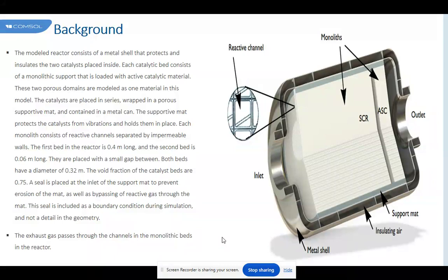Since heat is transferred to the exterior through the carcass, the ring monolith is expected to have a lower temperature than the core. Let us call the hot region the zone with temperature above 500 Kelvin. Slight differences can be seen when the core monolith is 900 per 2.5, where the hot region covers almost the whole core. At the same time, the cases with a 400 per 6.5 monolith in the core had a lower average temperature. The change in temperature between the core and ring zones may have an impact on the fluid distribution given the change in density.